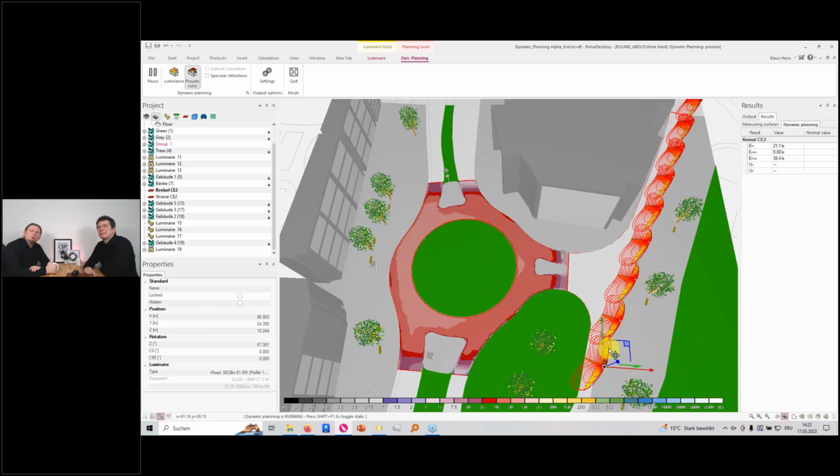Easy to change. Yeah, I guess from my side, it's also maybe good to keep in mind that it's a nice tool for sports lighting. If you have a simple sports arena, according, for example, to EN 12193, you also have horizontal values there, but beware, this is not the right tool if you go for vertical illuminances or camera positioning and similar stuff.